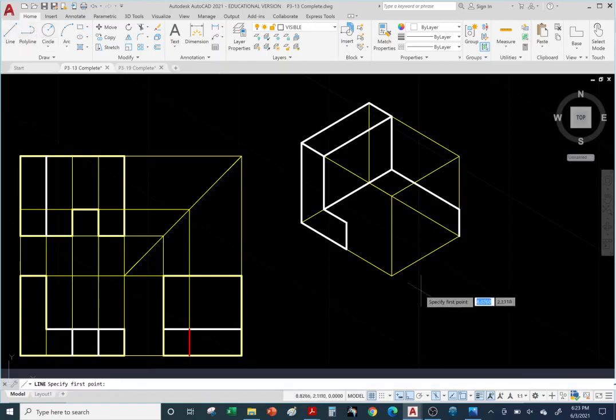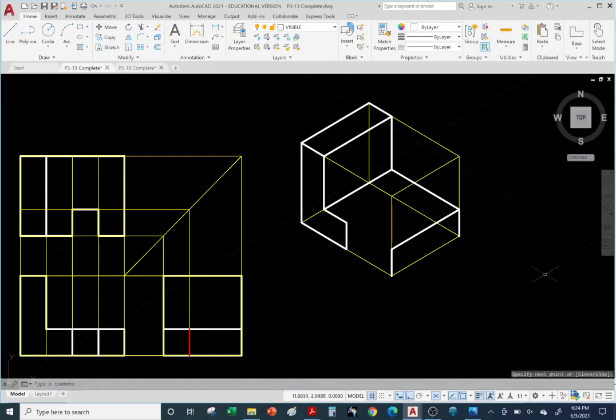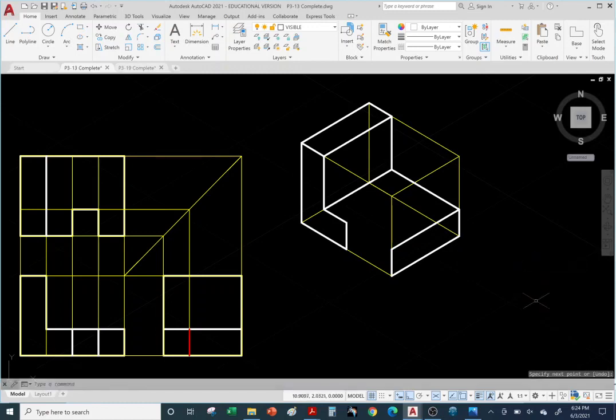Okay, so line command. This vertex goes straight up, 0.5, enter, and let me hit F5. There it is, hit the vertex and right click, enter. Okay, let me go ahead and draw this line to close that side off. Line command. We can always hit spacebar to repeat the same command, which is in this case line. Okay, right click, enter. We're almost there.